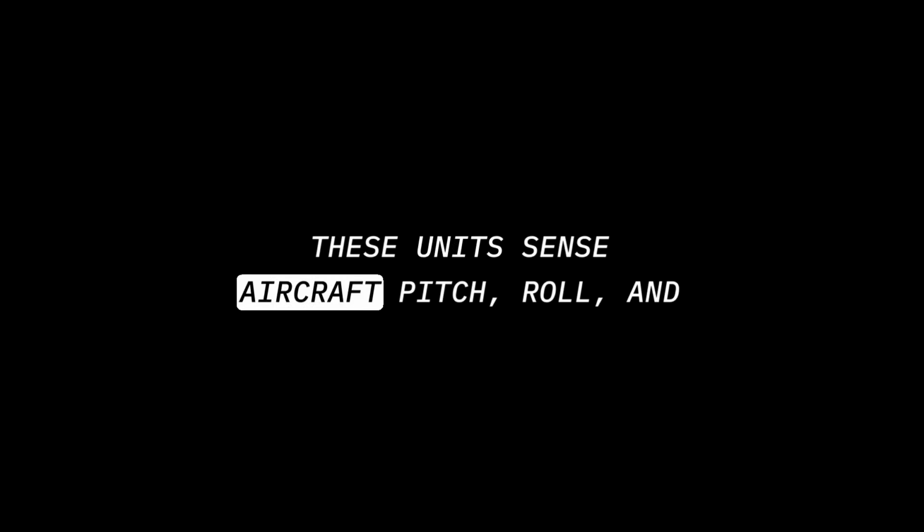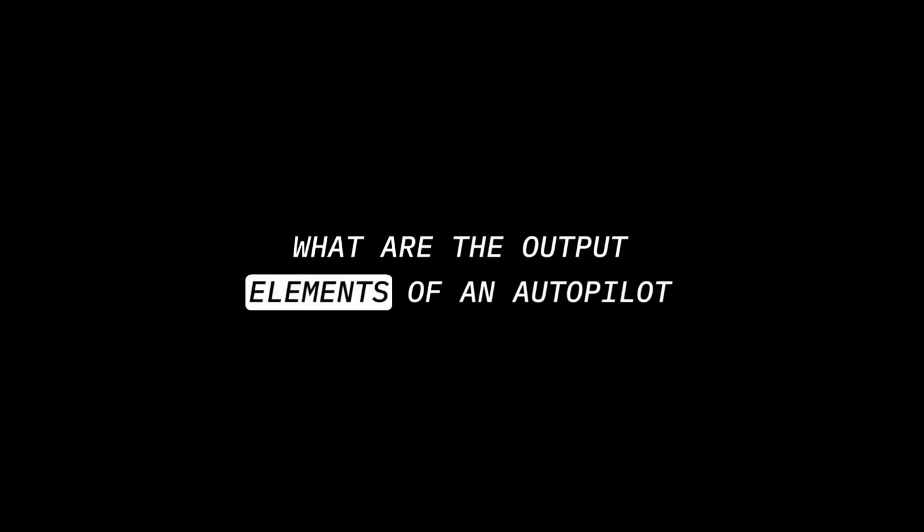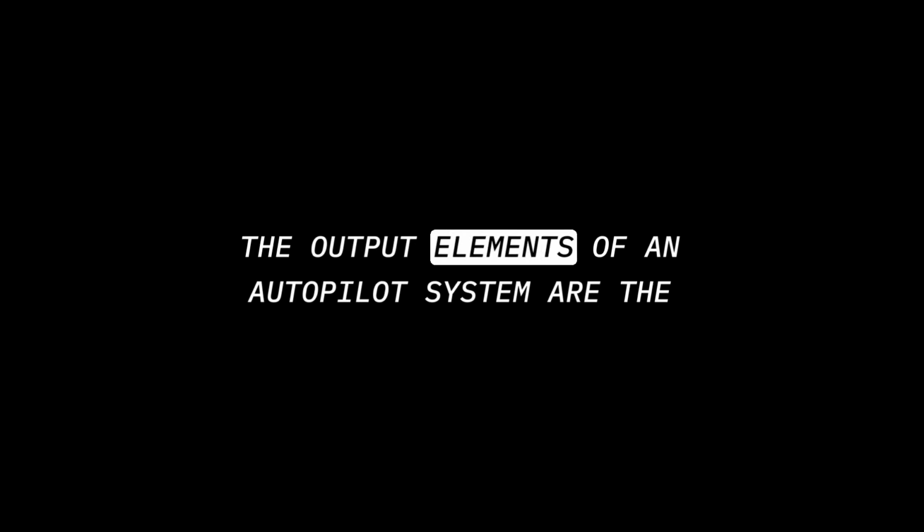These units sense aircraft pitch, roll, and yaw to automatically generate signals to keep these movements under control. What are the output elements of an autopilot system? The output elements of an autopilot system are the servos, which actuate the control surface. What are 3 types of servos used in autopilot systems? Hydraulic, pneumatic, and electric. What is the purpose of a bonding wire on a radio shock mount?